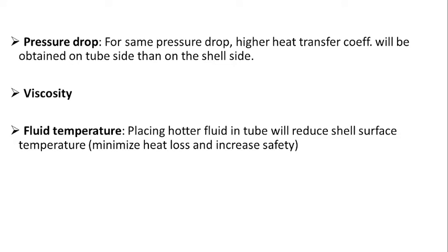Then fluid temperature. Passing hotter fluid in the tube side will reduce the contact with the shell surface and the environment. This will minimize the heat loss. Also it will increase the safety of the heat exchanger.